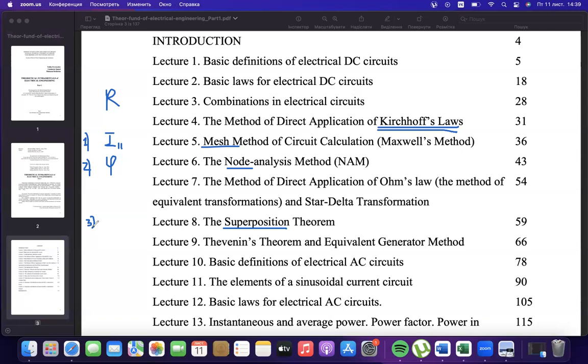If we have a couple of different sources, for example a DC and an AC source that operate simultaneously, we could divide them into different calculations. That is why, generally using this method, we could find everything. We could find all currents, all voltages, and all powers. But generally, it's used for some transformation of our calculational direction, just to represent something complex as a couple of simple parts, as a superposition of these simple parts.